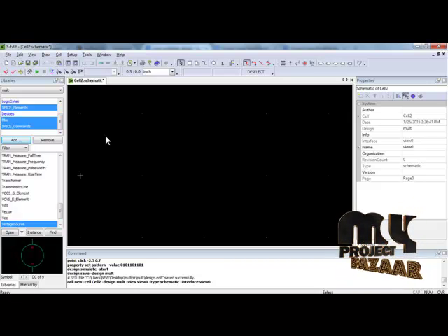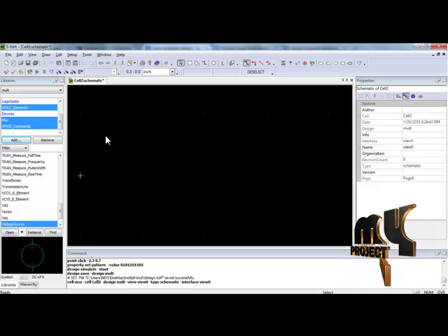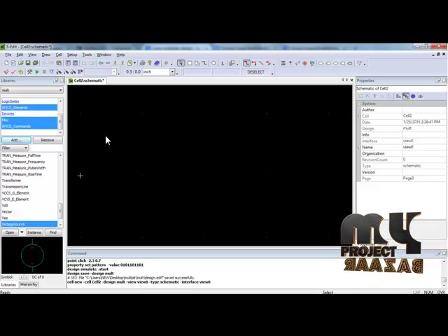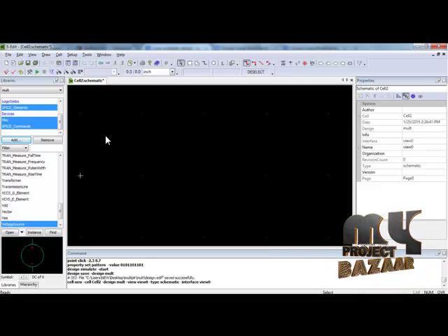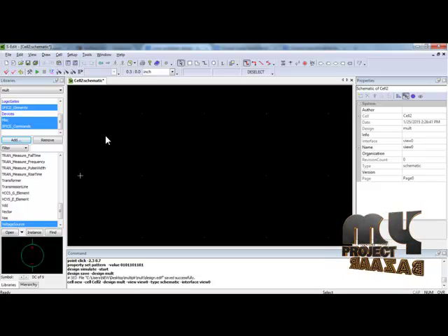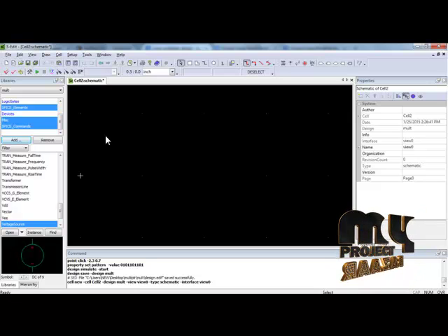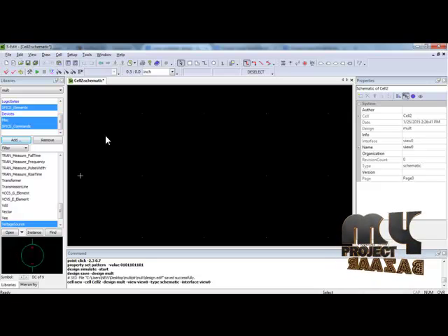And then after we design it in S-Edit, while simulating, the circuit's design will pass through T-Spice, which we can understand through the checklist generated through the SPICE code. And finally, while we are simulating, the timing diagrams will appear in W-Edit. Hence, commonly for our CMOS based designs, we will use mostly these edit tools, that is, again I will say, S-Edit, L-Edit, W-Edit and T-Spice.